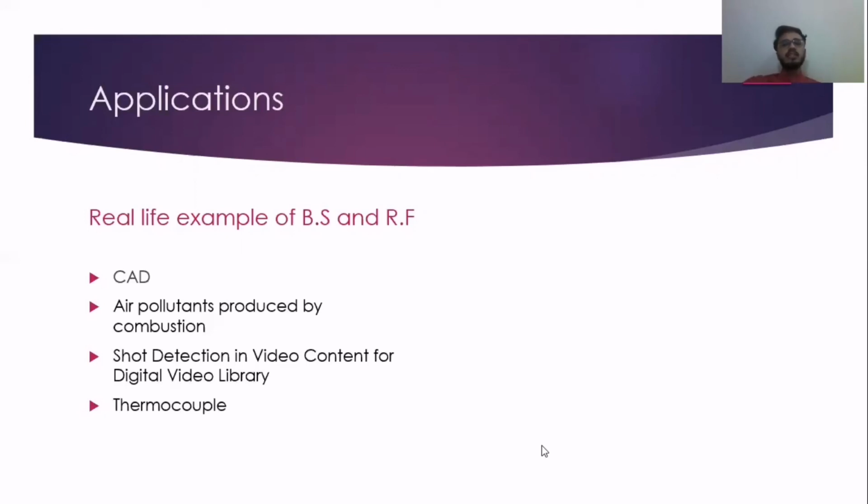But it is difficult as the equations describing the equilibrium state are stiff. So to overcome it, we reduce the system to one equation and one unknown, in which we can apply Regula Falsi and bisection method, but in its modified form. The method is modified through the introduction of an under-interpolation factor. By doing this, it accelerates the convergence rate. So in this way, we can find the quantity of air pollutants.